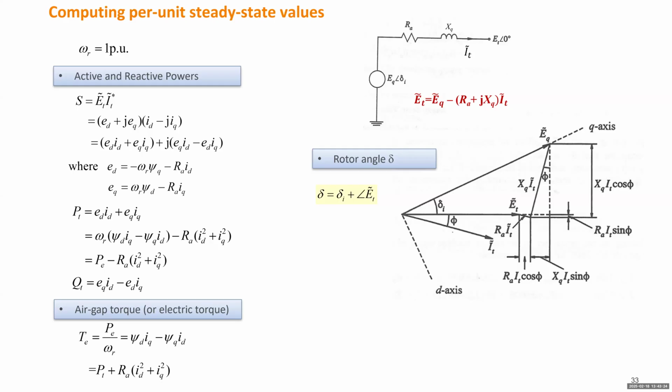All right, so we can draw a phasor diagram based on any equations about the phasor quantities. I assume everyone is very familiar with how to come up with this phasor diagram. To draw the phasor diagram, we need a phasor or vector representing each item in the equation, which has a complex value with real and imaginary part. First, you need to define a reference. If we assume ET has angle 0, we draw the reference, which is the x-axis, with 0 angle. So this will be ET. Okay, so start from ET.